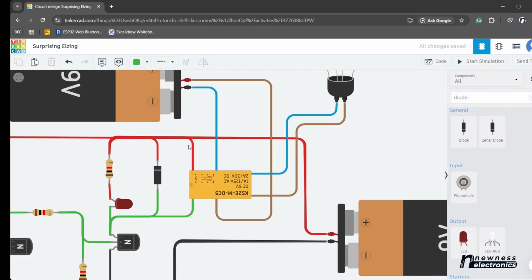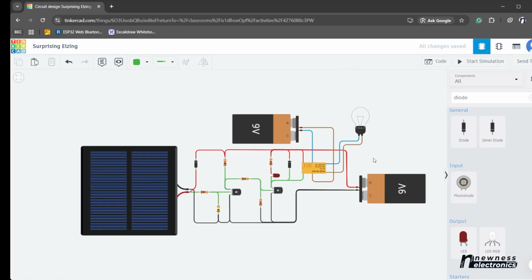So when that reverse current wants to flow back into the transistor, the transistor is already off at that time. This diode creates a pathway for the current to flow. So the current just flows through the coil back like this until it dies off. In that way, you can protect your switching device, which is the transistor in this case, when connecting a relay. All right, this circuit is already big and complex, but this is the first practical circuit we are building. Don't forget, this 9-volt battery is simulating your AC power supply. Do you get? So let's run this simulation and see how it behaves.